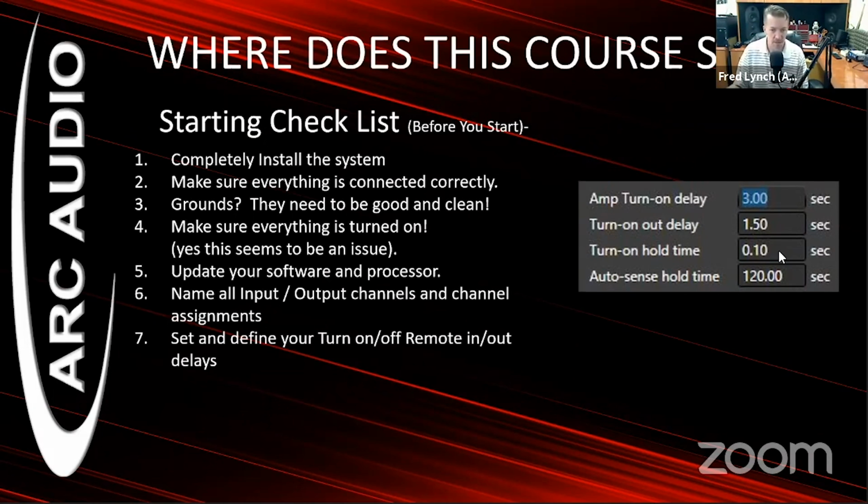And then auto sense hold time is if you are actually using an auto sense triggered system using either the signal detect or the DC detect. This will actually, as long as it senses the auto sense, stay turned on. But if it loses the auto sense signal, it'll wait whatever your defined number of seconds here is set to before it tries to turn the system off.